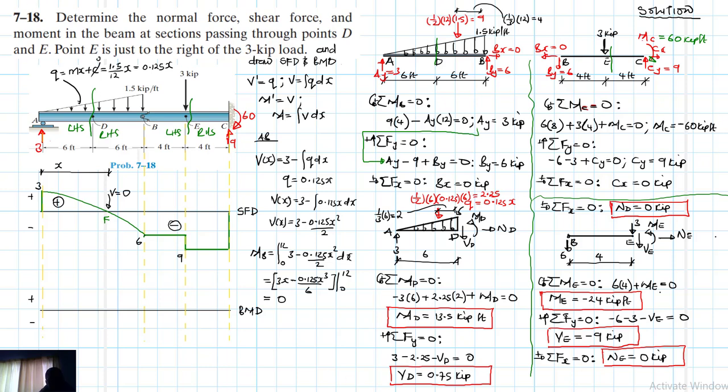Okay. So we are saying this point is A, and then this point here is B. So we are saying from A to F, the shear is positive and it is decreasing. So expect the slope of our moment diagram to also be positive but decreasing. So you will expect something like this.